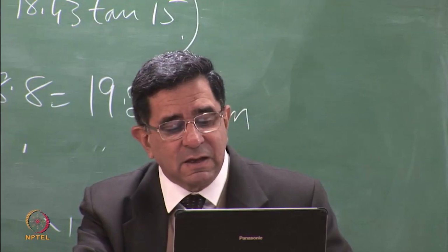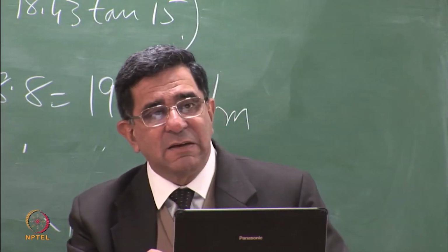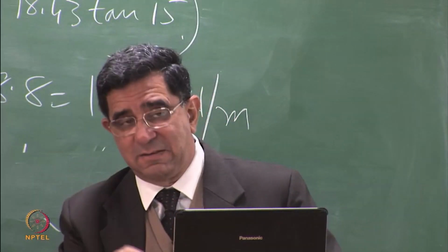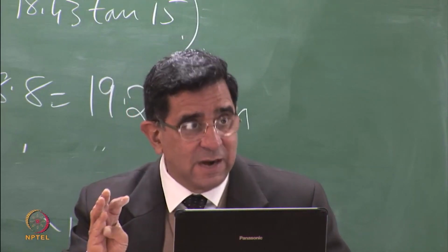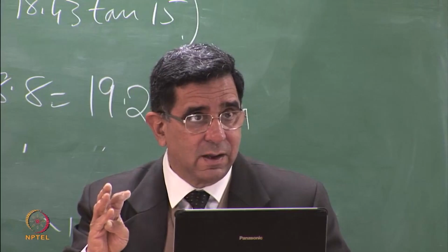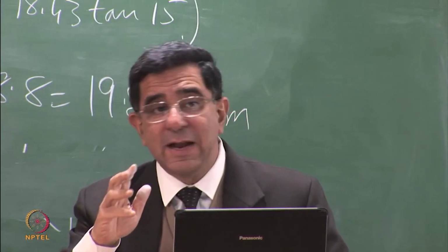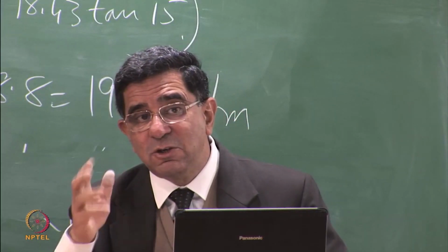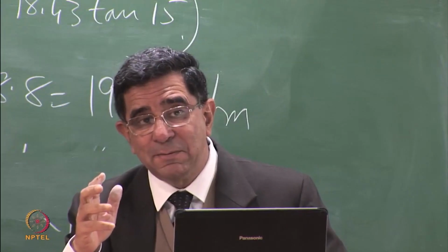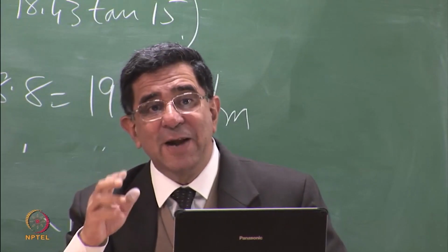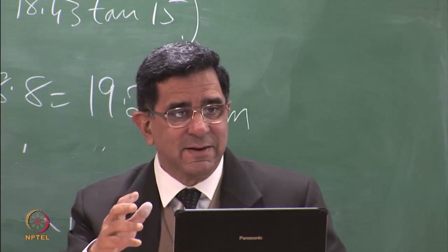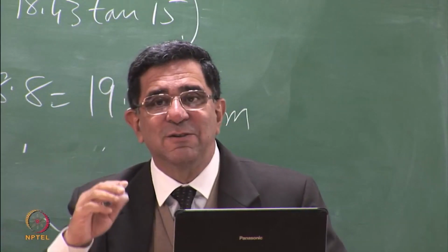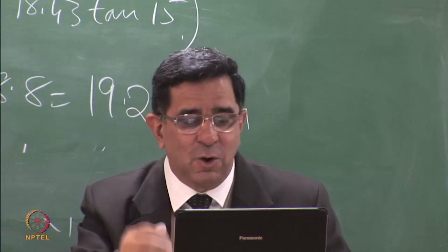So with this, I'd like to close that this is just one of the cases. What we have done just now is without seepage and without earthquake. But I have shown to you the interplay. If I reduce W, what will happen? That 19.2 will become lesser, because it's all coming from the weight. So there's a tendency to reduce the thickness of the layers so that the T can be lower.